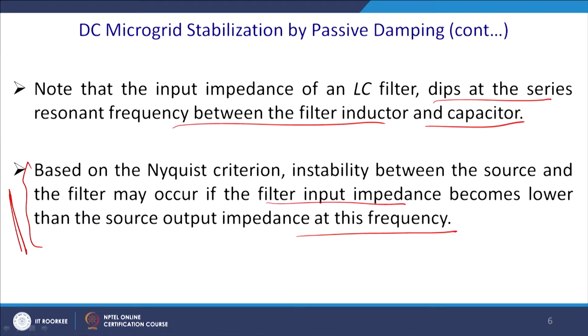So, you have chosen a particular switching frequency, and a layman kind of question is sometimes asked: what is the frequency in the DC microgrid? Because all these DC to DC converters are switching devices, they operate at a particular switching frequency, and you are required to filter out those high frequencies. While designing the filter, you must remember this Nyquist criteria very well.